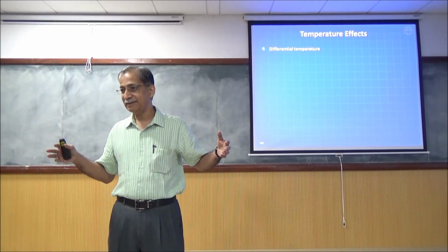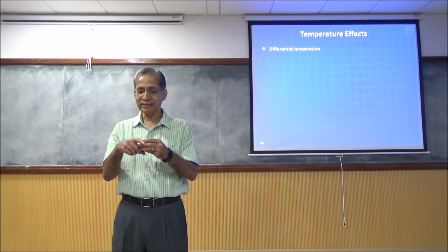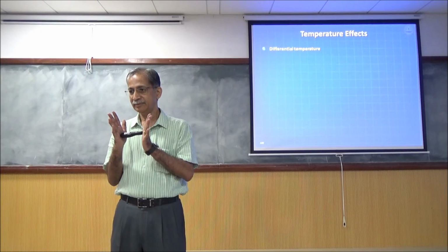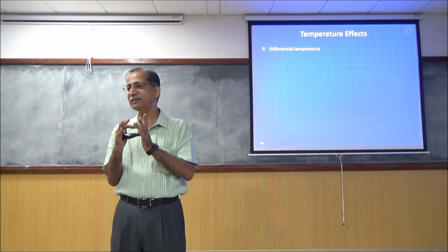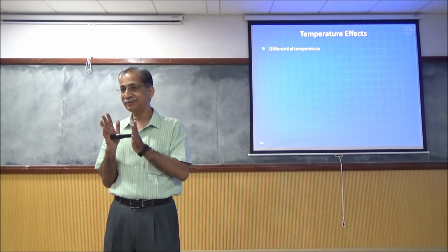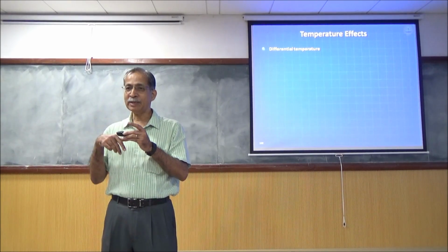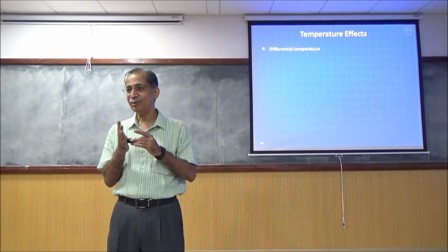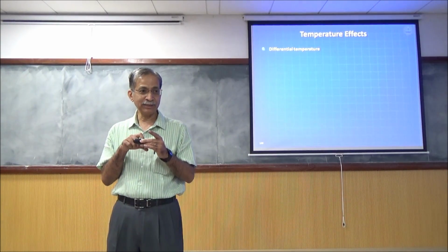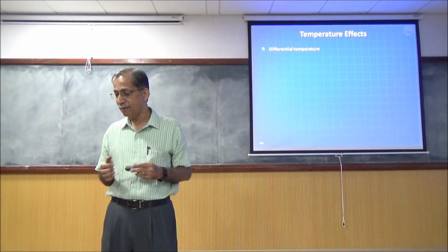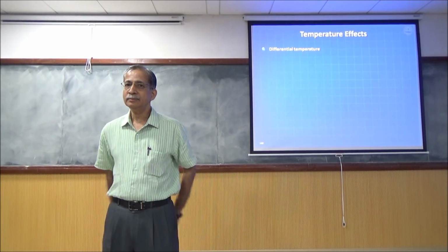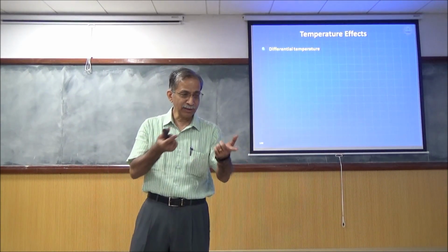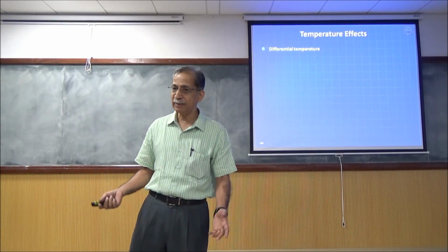If you do thermal analysis, let's take a simple beam. And let's say the two ends are restrained. And you have a change in temperature of 70 degrees Celsius. Let's take the worst case, that means you cast it in the hot summer and you are now in winter, so it's actually reduced in temperature, so there will be actual tension. How much will be the actual tension? Normally beams you don't design for actual tension, but this beam will have actual tension. How much will it be?